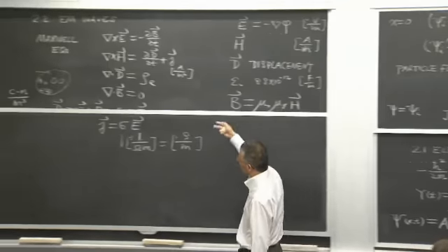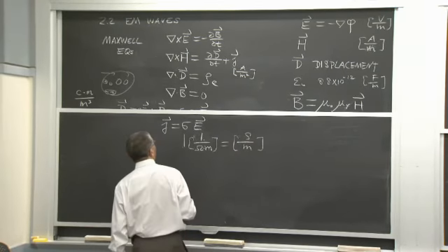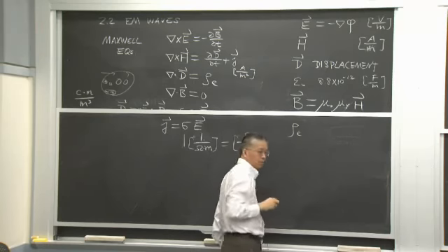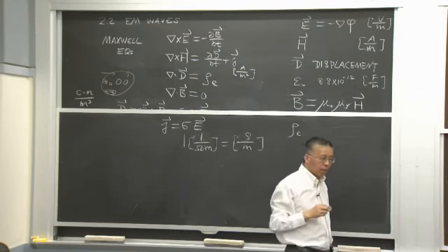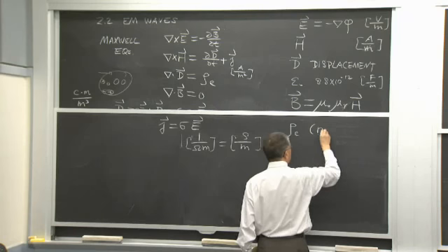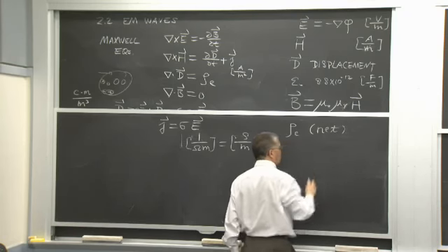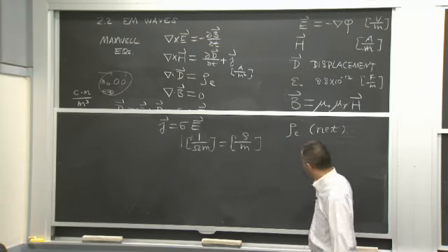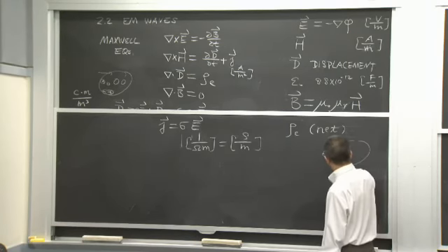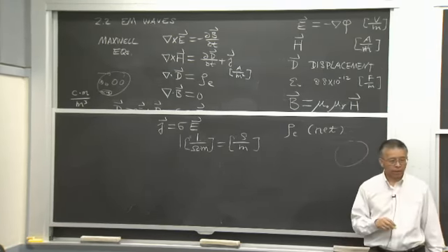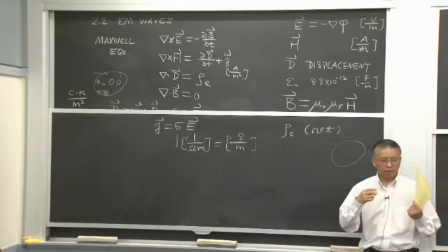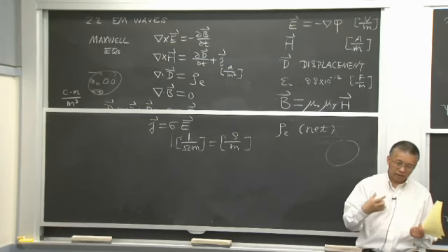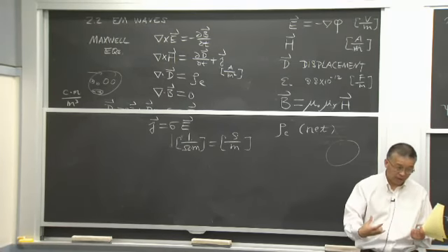Okay, so we have all these quantities. And further, what is rho, say the charge density? Right? And this charge density is the net charge per unit volume in the material. Okay, so if you have a semiconductor, right? In a semiconductor, you can have a positive donor, right? When, say, if you put a phosphor there.